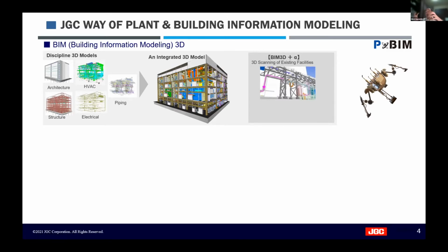For example, we design the plant, and after we build the plant, we scan, we call it laser scanning, and then we can see the differences between the built one and the engineered one. And we also sometimes place equipment 3D models, which is actually not just a box, it's like a working object of equipment such as pumps, compressors, valves, and those things.